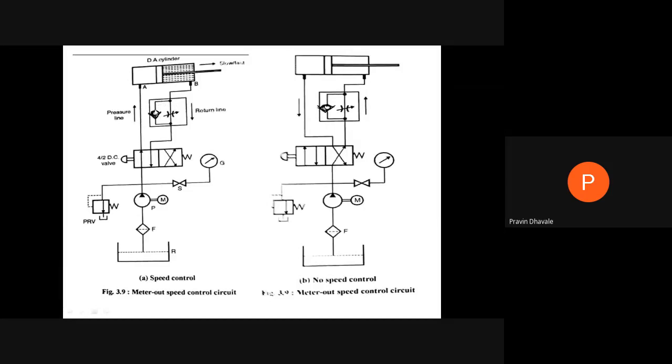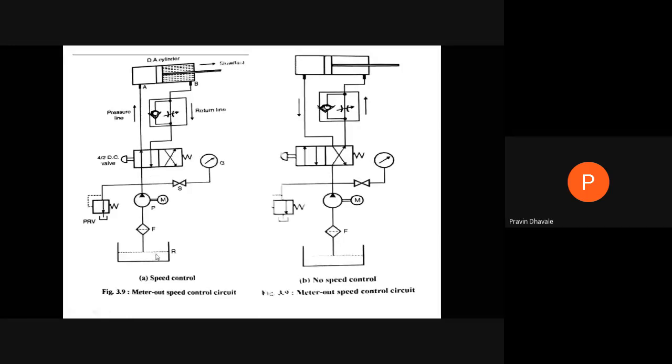So the flow comes back, and all of the fluid coming from port B must pass through this variable flow control valve, right? And after that, it will pass through this port B to this port, that is the R or reservoir. It comes directly to this reservoir. Are you getting it? Here there will be a reservoir port. Imagine that: this is port P, P for coming from pump.